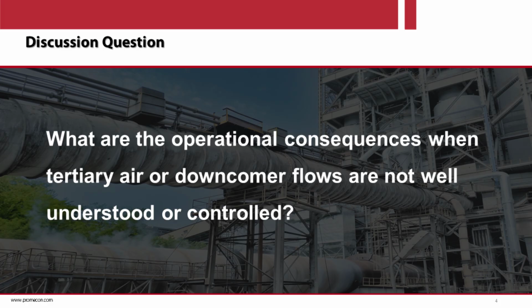Yes, thank you for that question, Xavier. One of the first symptoms the controller will see is, of course, an increase of CO at the calciner, but also at the kiln inlet. And potentially, of course, both could, it's like an addition. You could have that at the stack.